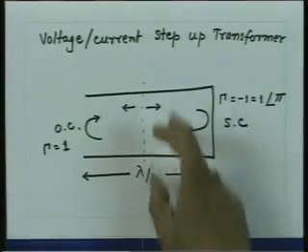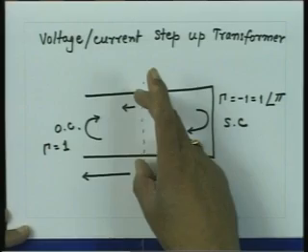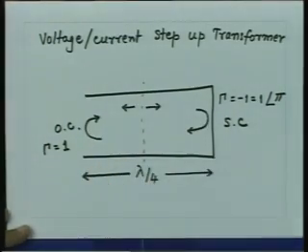So, this process now can be used for your advantage, that the voltage which you measure on transmission line could be much larger compared to the coupling voltage at this location. Or in other words, this resonant section of a line can be used as a voltage stepping up transformer. Precisely this is the application we are talking about, that take a voltage source which is a small source which you connect to this resonant section of a line, and if I measure the voltage on the open circuit of the line, this voltage will be much larger compared to the coupling voltage on the line.